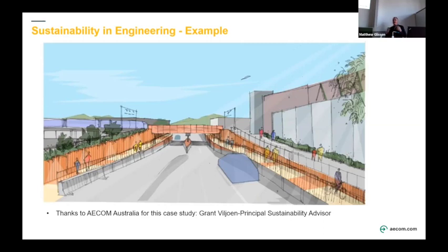Yes, I mean we have our performance criteria, don't we? And I would sort of loop this back to the whole GI. If we have more information on GI, when we're doing pile load testing, we of course would be more conservative in our design if we know they're going to be tested. That's with my Keller hat on because I used to be a contractor.